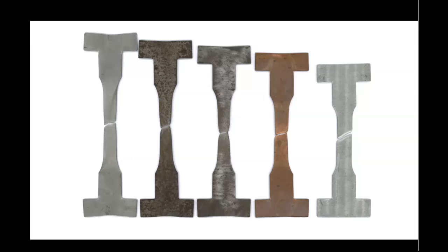Last multiple choice question: which statement best describes the modulus of resilience? So resilience is really how much energy a material can absorb without breaking, right? Think about it, we want to have resilient springs, resilient structures that deform only elastically and don't deform plastically. So we're only looking at the area up to the yield point and no further. We're only working within the elastic region.